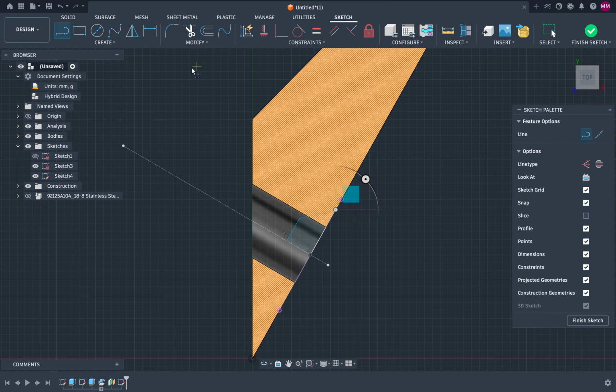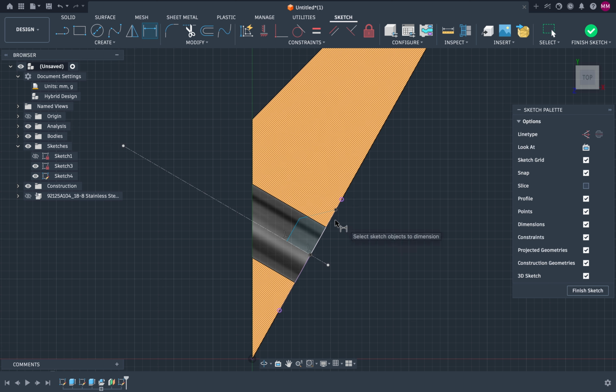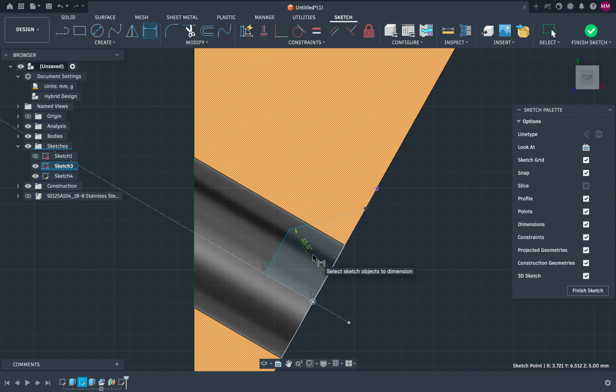Now we need to get the angles right, and I know that this bolt or screw that we used has a 90-degree angle combined, as it was shown in one of the diagrams, so we most likely just need a 45-degree here. And I also know that it extends by 8 millimeters from the center line. So click on this center point, hopefully. Well, let's just use this one.